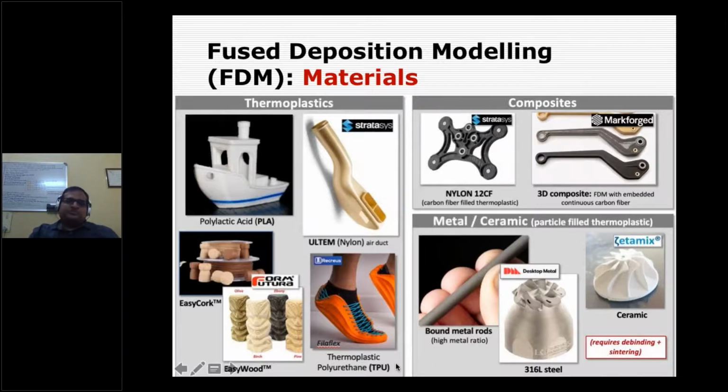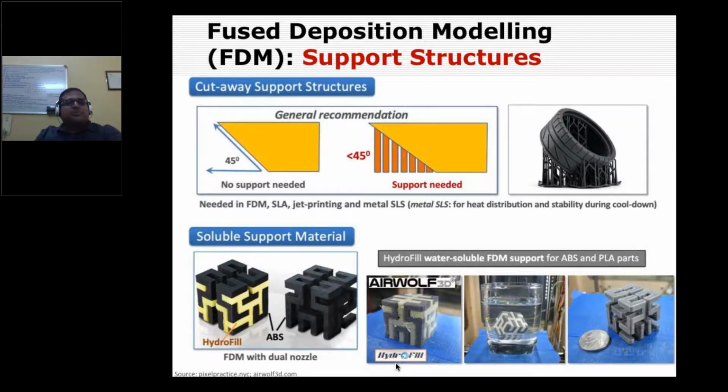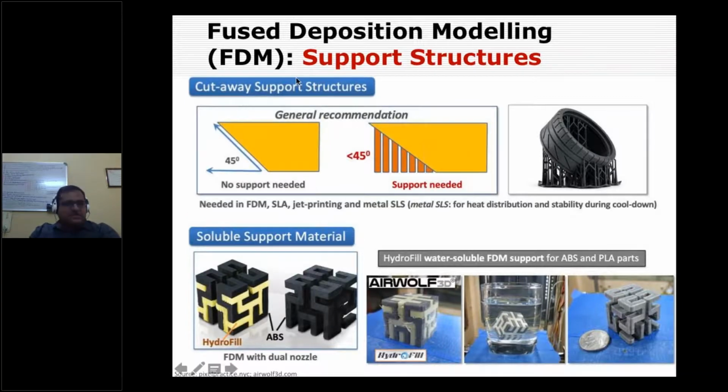And of course the support structures, as we know the supports are critical in any FDM machine, so we need to give special care to the supports. There are some thumb rules for giving supports, so use those, and you print the supports along with the model. You may have a soluble support or a breakaway support, and you can change the support structure or play around with it.